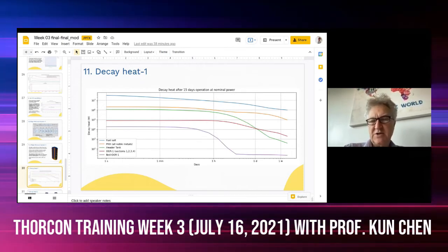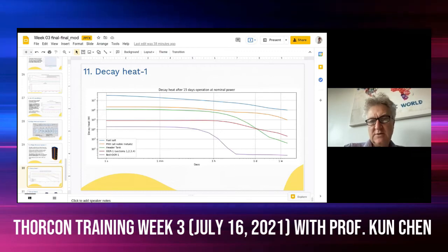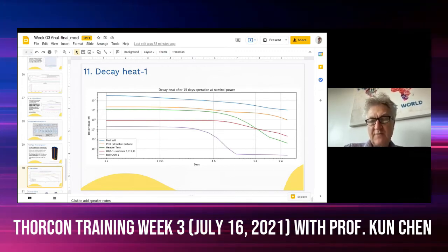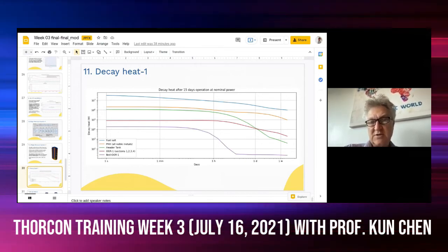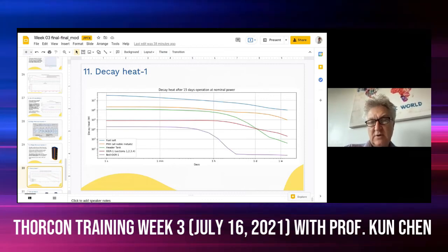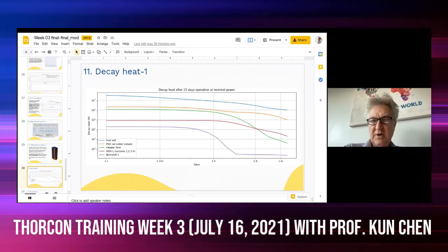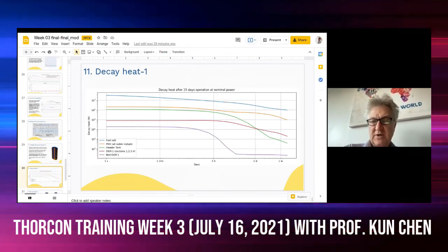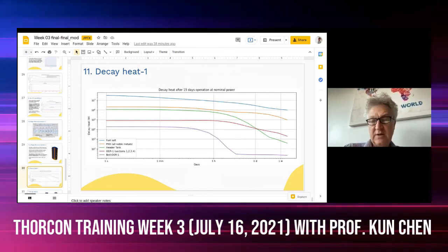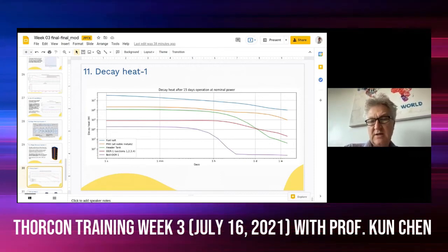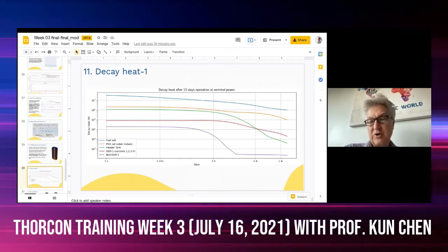That allows us to change the power output much more rapidly because the steam system is at very high pressure, so it has very thick components, and you can't change the temperature very fast on those components because the thermal inertia of thick steel is such that you'll create internal stresses within the steel and you'll get thermal fatigue. So the goal in the design, any place you have thick steel, is to keep the temperature constant.